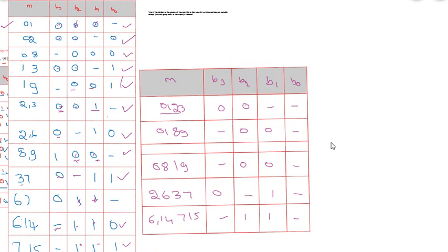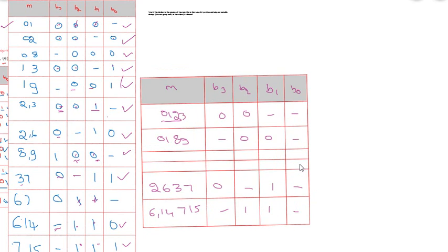Similarly, the term 0 1 8 9 is similar to 0 8 1 9, because both have the first bit as dash, then 0 0, then dash, so we can leave this portion also. From this, no other group is the same, because 0 1 8 9 is not equal to 2 3 6 7, which are different minterms, and 6 14 7 15 are again different minterms, so these are not the same group or duplicates. So in step 3 we got 4 groups.